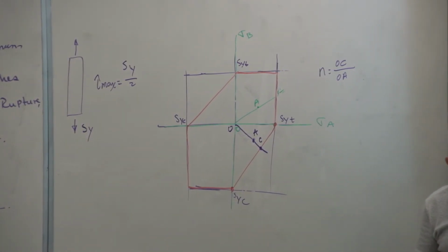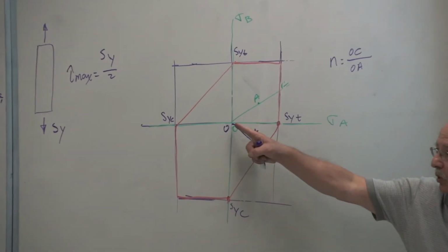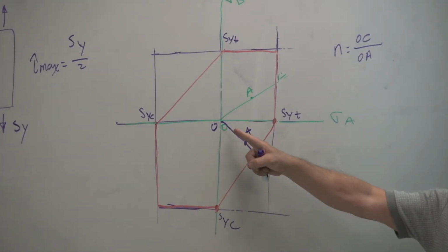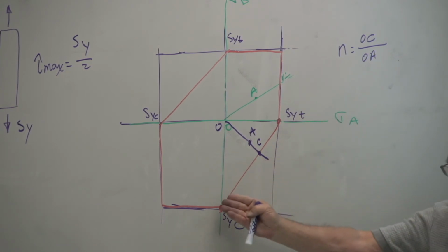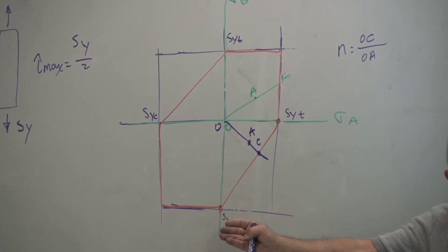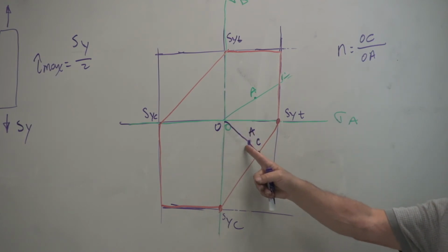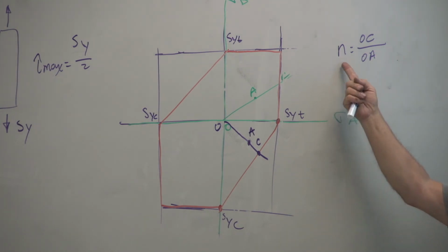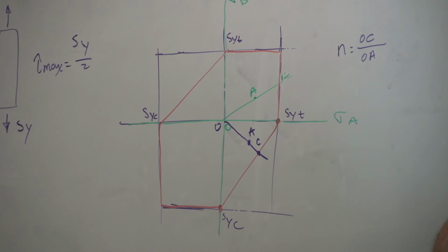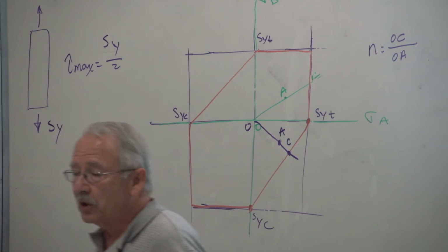So we have two curves, or straight lines in this case. Load line, that's along which stress is being increased. Strength line, limiting value of the stresses. Whenever they cross, start of failure. The ratio of increase of stresses before you get there, factor of safety. No different than what we had before. But of course, the numbers will be a little bit different. Any questions?